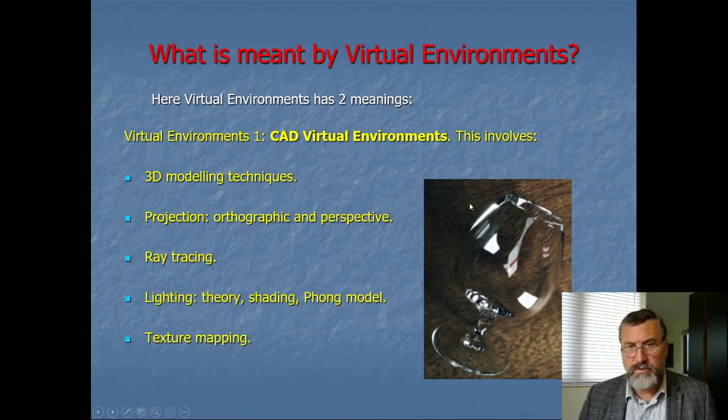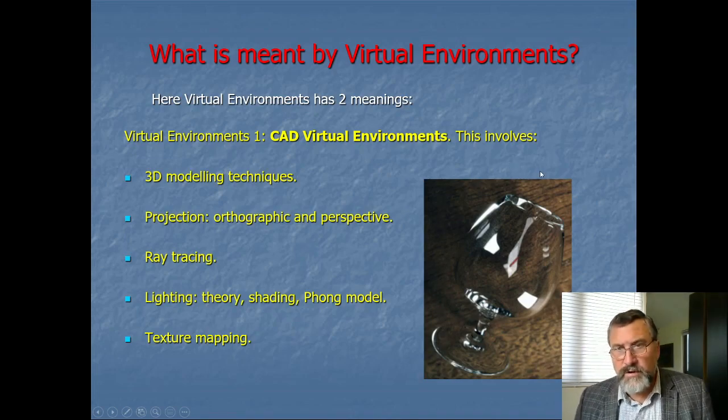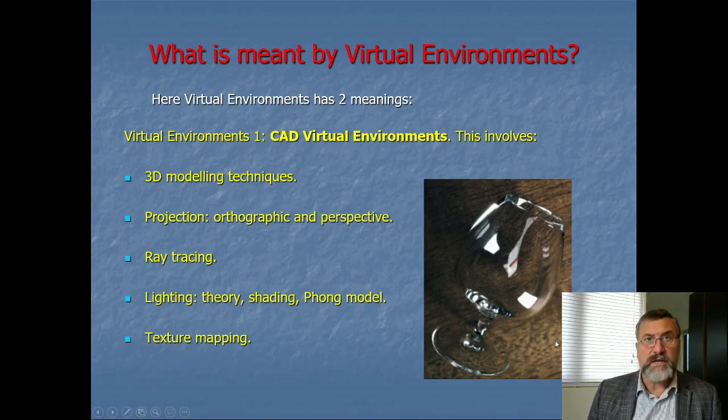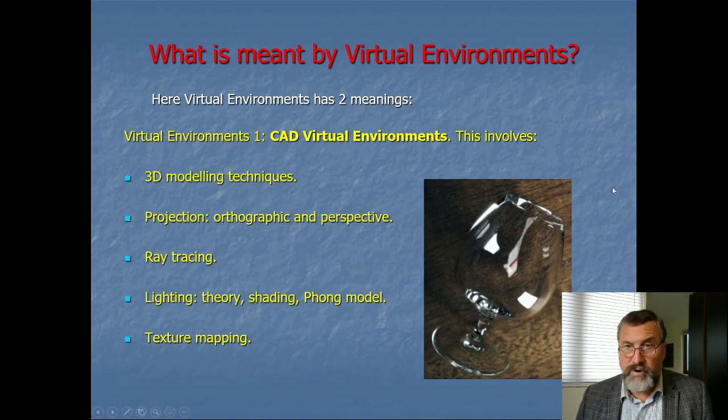Texture mapping is something interesting because normally you put a bitmap onto a surface in a CAD system like AutoCAD, and in something called 3D Studio Max, which is their virtual reality software. And then that gives you something looking like a table. What we were talking about here is putting a 3D texture on there as well, something called a bump map. This is more of a researchy thing. And then when you arrange the virtual lighting, it will reflect off this bump map in interesting ways and make it look really realistic.